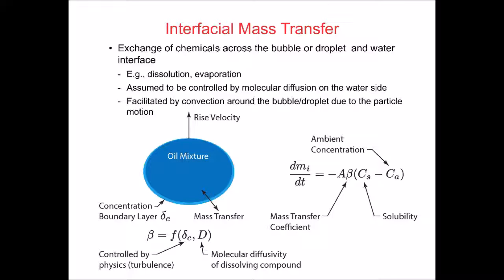In the one model, it says that the bacteria are going to reduce the hydrocarbon mass just by first-order decay. And here we don't need to know the droplet size, we don't need to know the surface area, we just need to know the concentration of the oil in the water and the rate that the bacteria are attacking that oil. And this gives rise to exponential first-order decay.